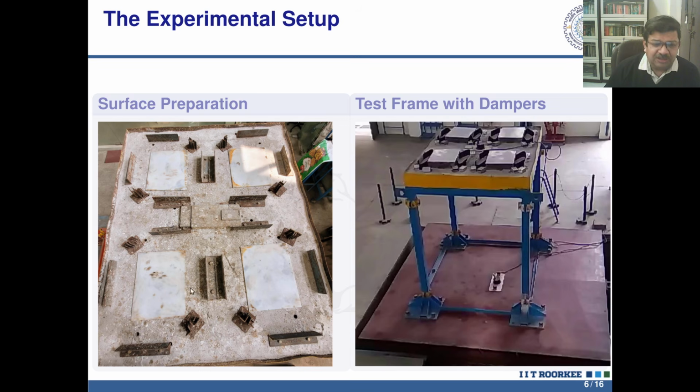Now, in this case, I used these steel angles to make slots to house these blocks. It is quite possible to make this roof slab as an inverted waffle slab, and that will have these slots available ready-made, where this surface can be prepared and these mass blocks can go in with springs inserted in between.